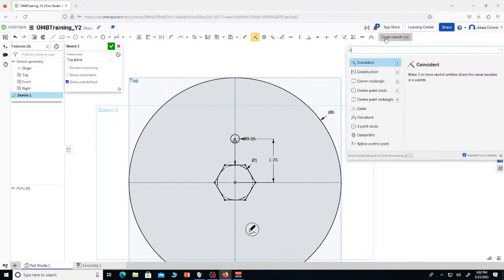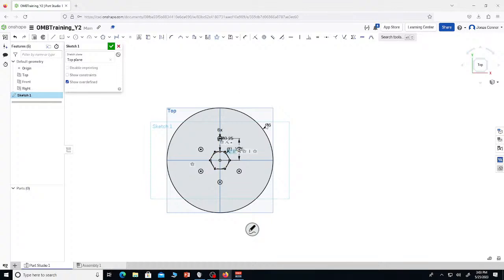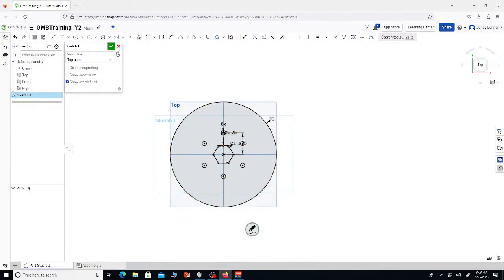And then I can circular pattern it. Can select this. And there's a little square in here in the middle. I can move around where it's going to circular pattern it. We'll just have that be in the middle. I want 6 of these. And boom, holes. And so when you're modeling a robot, it saves a lot of time. It's very useful to do that.